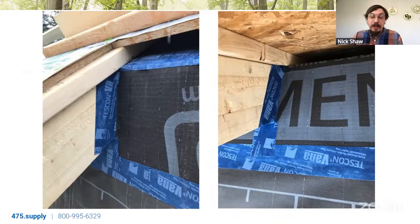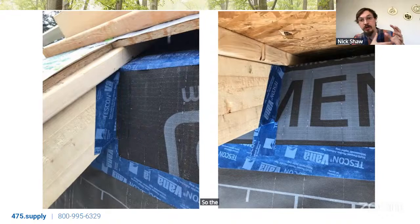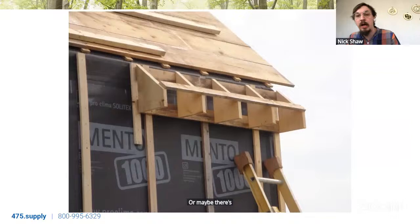Yeah, the insulation is inboard of the membrane. So it'd be behind this membrane. I would say this is most likely a cathedral ceiling, so the insulation is following the shape of the roof. And all of this, the membrane is concealing the sheathing, which also then has insulation behind it, or maybe there's a rigid board behind this.